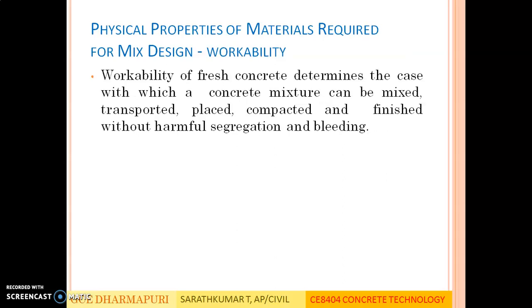Workability. Workability of fresh concrete determines the ease with which a concrete mixture can be mixed, transported, placed, compacted and finished without harmful segregation and bleeding. Segregation is the separation of coarse aggregates from fine aggregates and cement, whereas bleeding is when there is excess water in the concrete mix, it tends to come to the top and remain there. It is called bleeding.